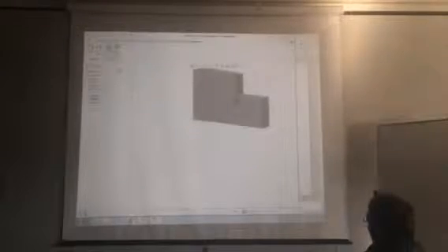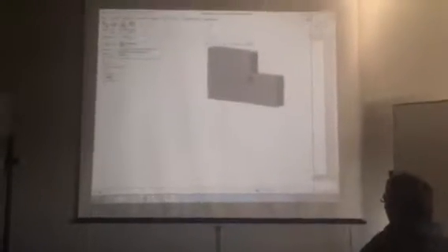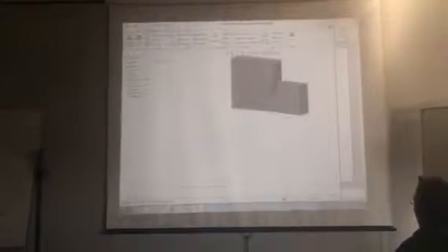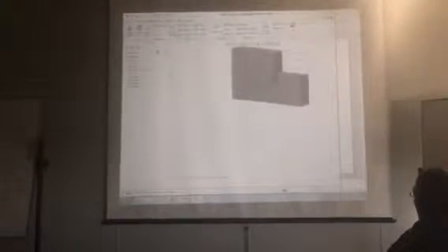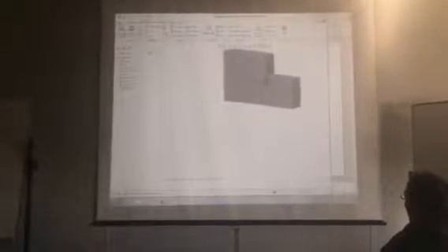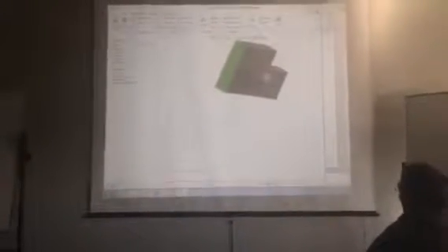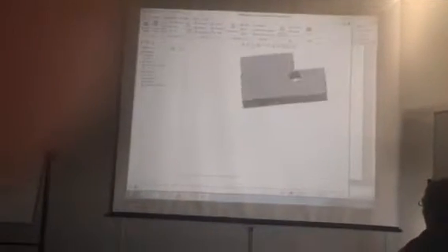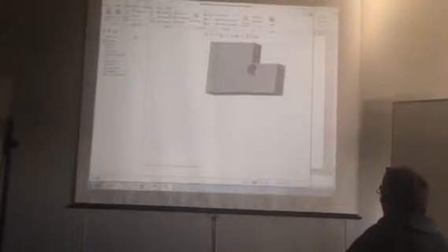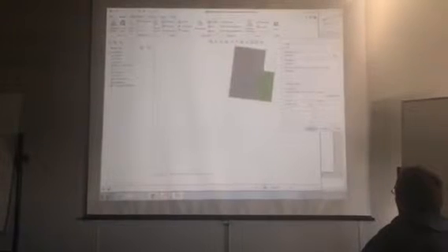Before Creo, when it was Pro E, Pro E4, it was called Mechanica, before it was called Simulate. It's the same thing. It's got all this stuff here for thermal modeling, and we see here our usual sort of mechanical modeling. So I'm going to say displacement. I'm going to put this edge here and say that face isn't moving at all. And what I'm going to do then is put a force going down on this face.